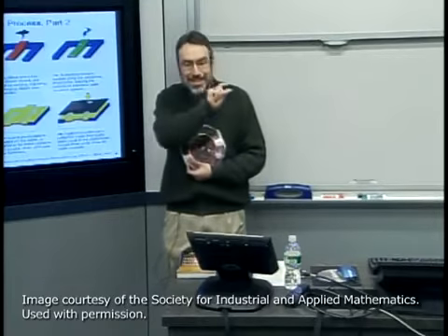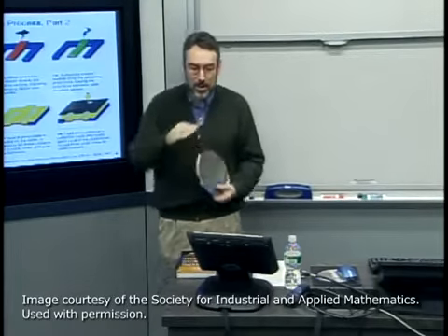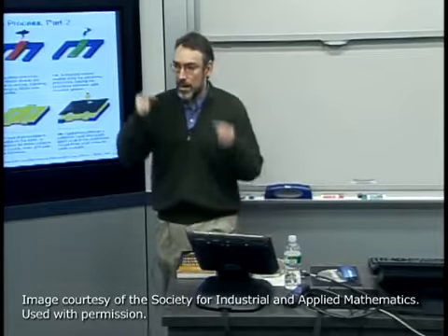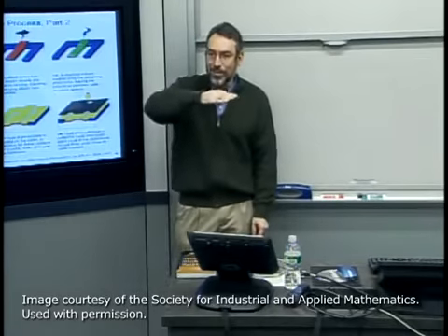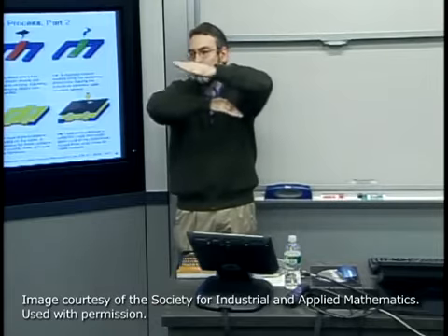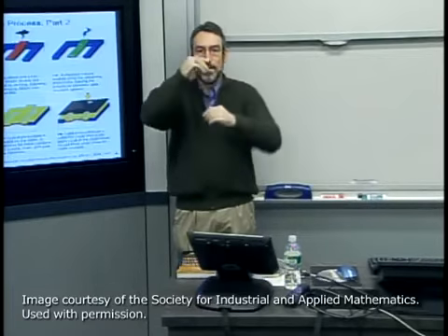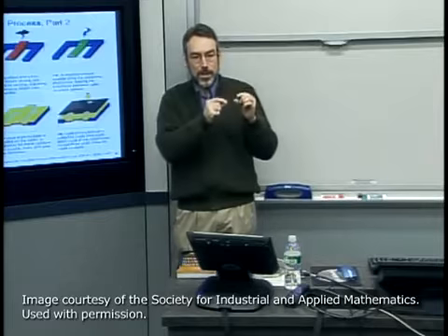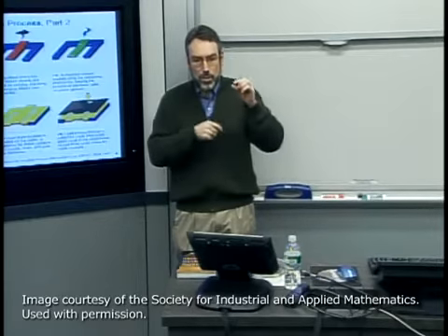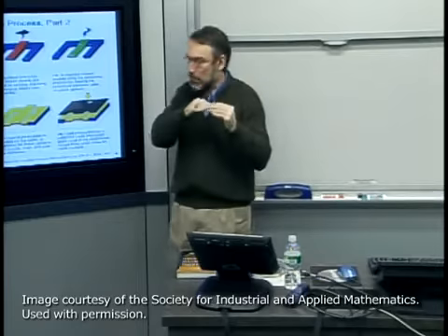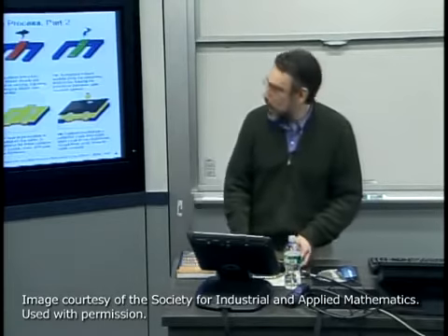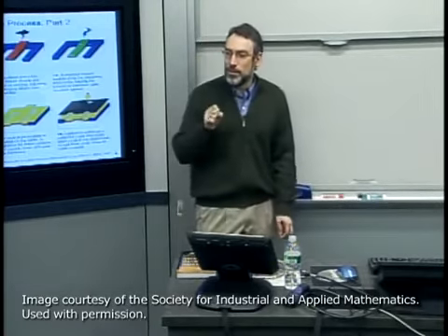They're imaging slices of that so that they can do all kinds of other on-the-fly alignment control as well as leveling, because it turns out the depth of focus is a big constraint. And if I have a focal plane mismatch where I'm in focus on the left side of the chip and not on the right, then I don't get the dimensional control I need.